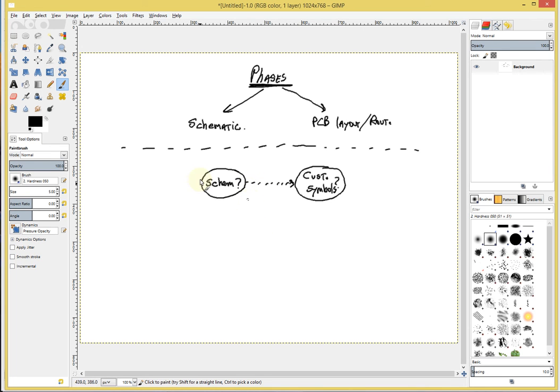After you are done with this stage, the result is that you produce a file, usually called a netlist, which is a file that encapsulates all the electrical connections of your circuit. That is imported into another component of the software, which is usually separate. And this is how do I do PCB layout and routing.